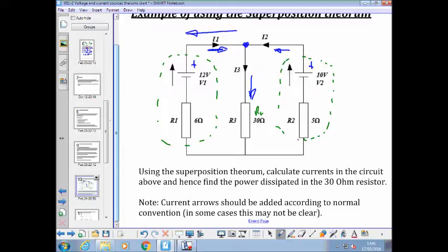Two batteries with their internal resistances from our previous model. So that could be a simple battery charger, that 12 volt battery charging that. And if it is, then that current is going to come out negative because it's actually going to be going that way and charging it up. Alright, but let's find out what answer we get when we follow that through.